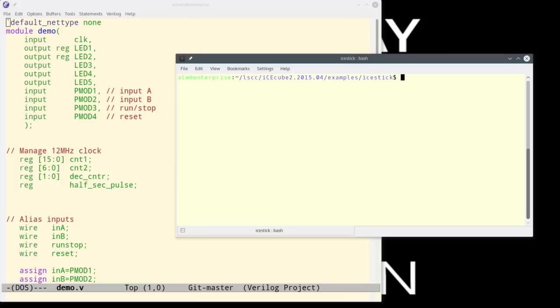And the place and route tool needs to have some digested Verilog, and that's going to be the job of another open source tool called Yosys. So we're going to use those tools in concert. The instructions for setting all that up are on the IceStorm page, which you can get to with the article that goes with this video. You really need to install the latest versions, following the instructions there. If you use Ubuntu and you've got a repository, it may have a version of these tools in there. They may not be up to date enough to get the job done.